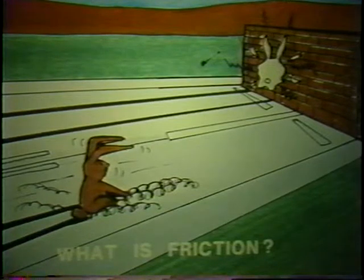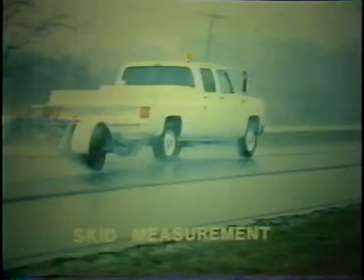Friction is affected by pavement drainage, vehicle speed, pavement texture, and aggregate selection. Pavement friction is measured by a locked wheel skid trailer. The standard test speed is 40 miles per hour and is reported as SN40, or skid number at 40 miles per hour. Uniform specifications should be followed when measuring friction.